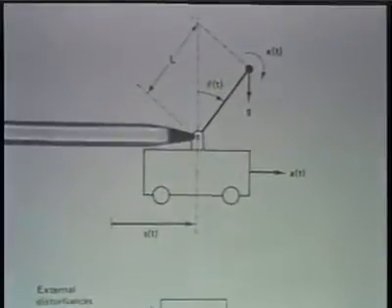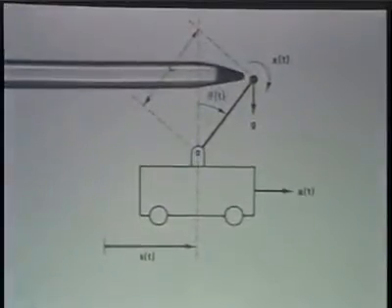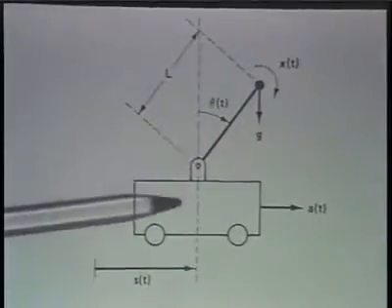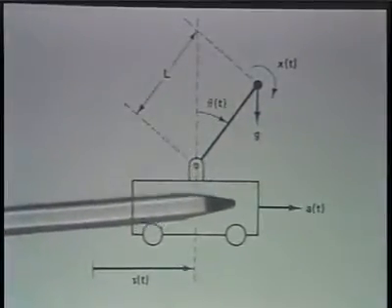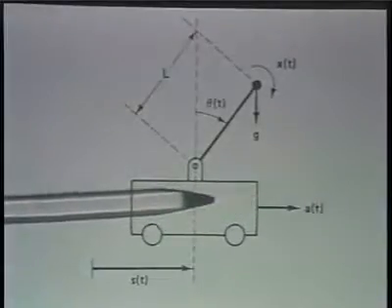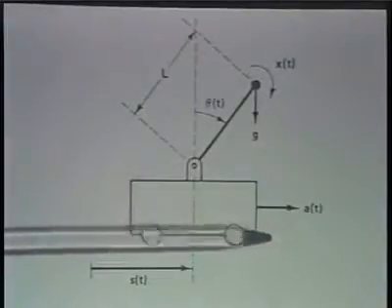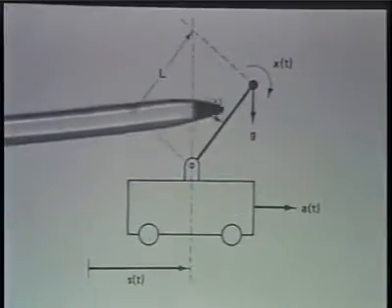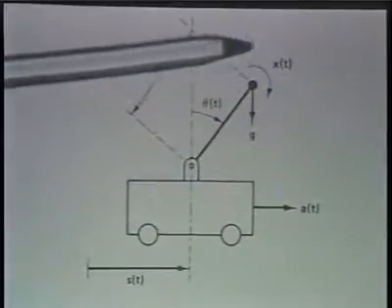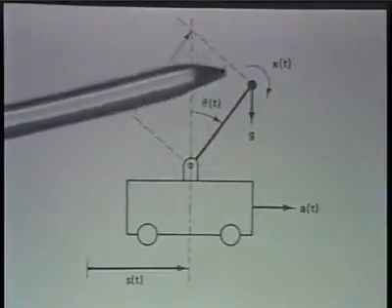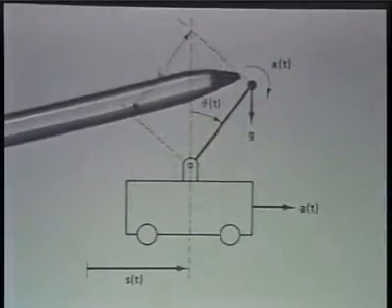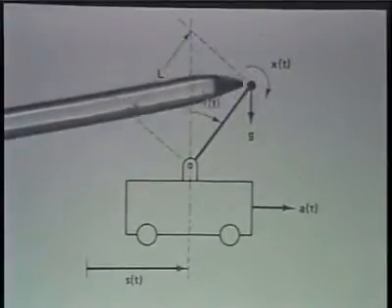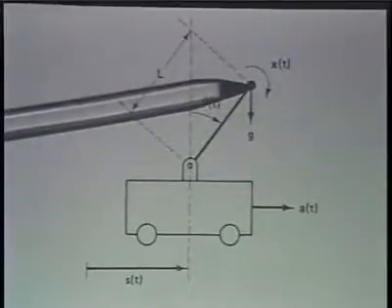Mounted on the cart is a rod with a weight on the top, and this then becomes the inverted pendulum. And the cart has an external acceleration applied to it, which is the input that we can apply to the system. And then, in general, we can expect some disturbances, and I'm going to represent the disturbances in terms of an angular acceleration which shows up around the weight at the top of the rod.